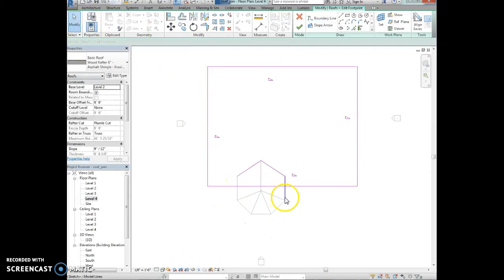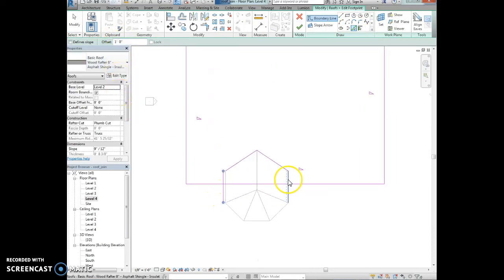Well, I guess I probably should have read the instructions before I went doing this. I'm going to delete these two vertical lines, select the Pick Lines tool again, set an offset of 1 foot, and then I need to select the two vertical lines. There we go. And then I'm just going to join all these together. And also I have to join my boundary lines, right? So this isn't a continuous boundary. This pink line needs to be removed, and then these need to be shortened. So you have to use your trim tools like we've used before.